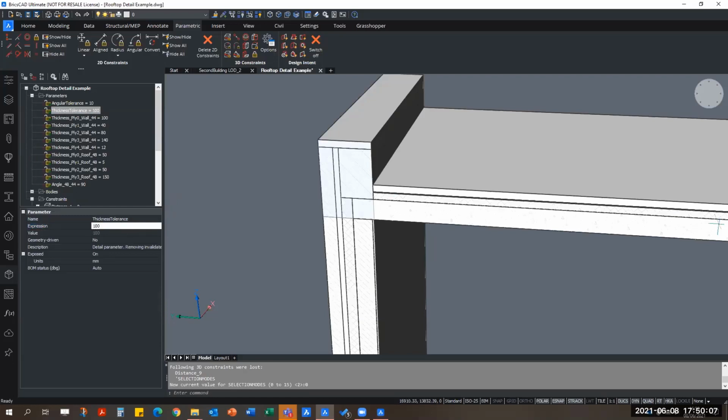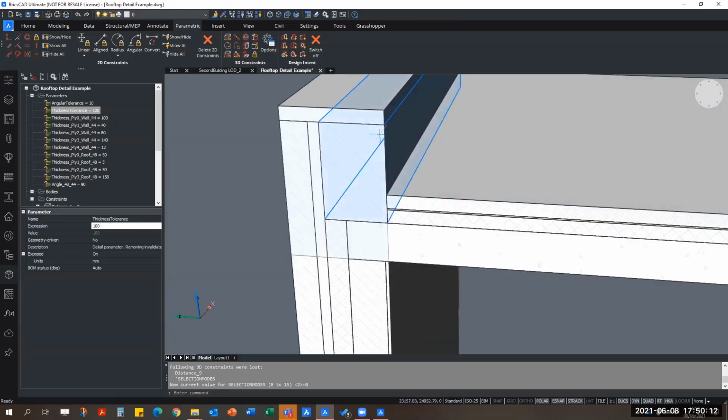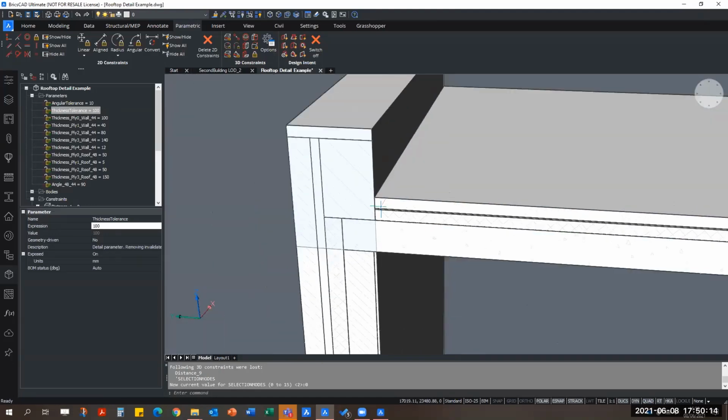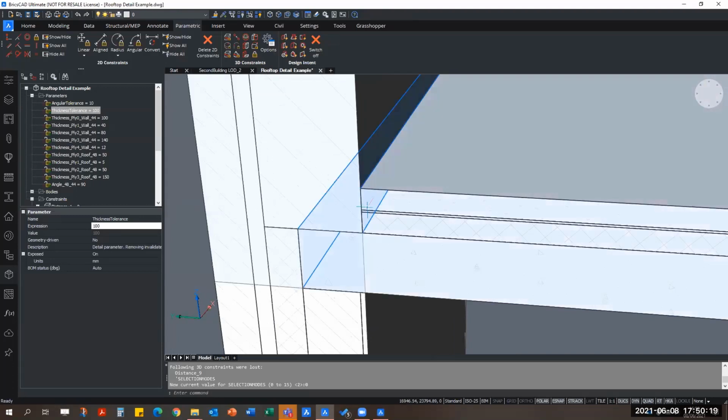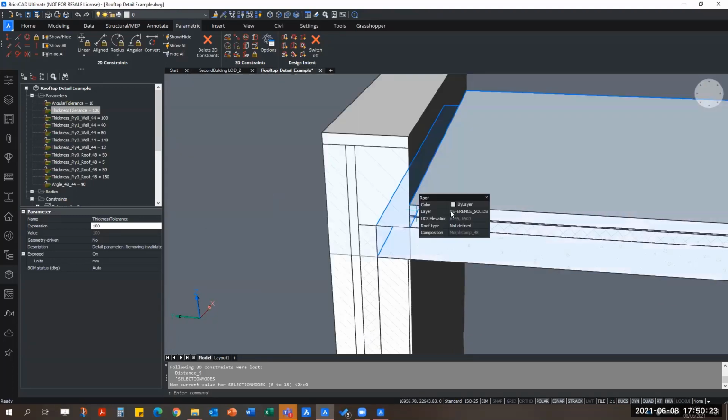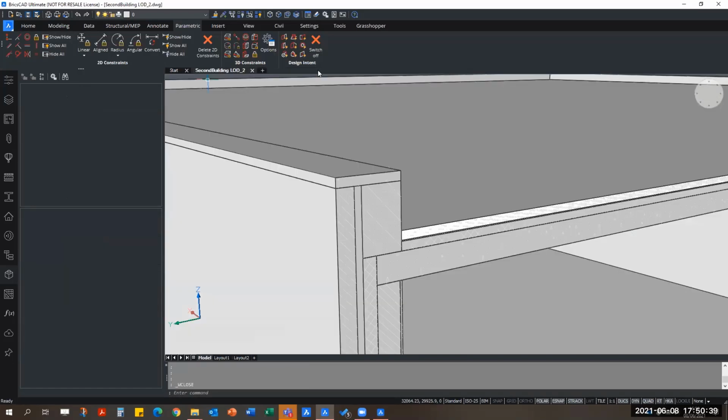So what the thickness tolerance does is that it will accept things not specifically to apply, but in most cases, areas within the 100 mil range will automatically fit this detail to that particular part of the model that you may have, because in different projects, you may have a different composition, which means you have a different thickness. Once okay, click save, and you can close it.